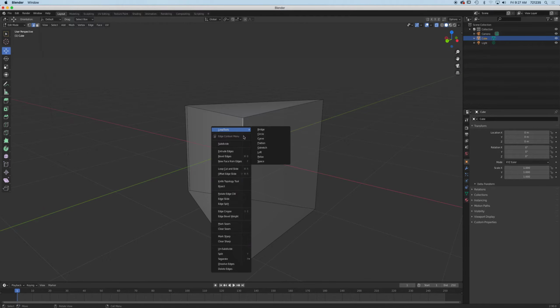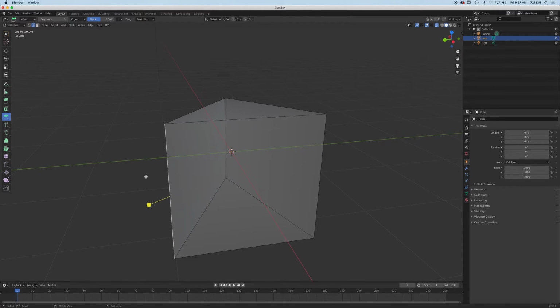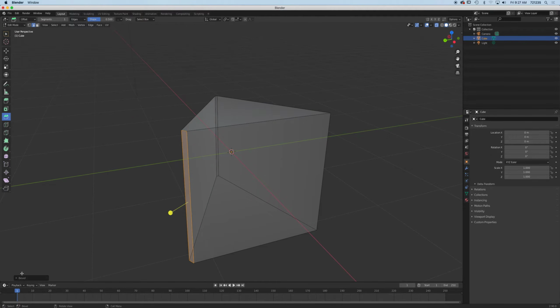I'm going to right click and then bevel, or let's use the bevel tool right here. This one. Okay. While it's active though, that thing will always be on, so I'm going to bevel that real quick. So you see what happened? I just put 2 lines right there, and then you can expand that to multiple segments, but we don't want just one, right? So select that one. Bevel is still active, good. So be careful when you use these tools, they're alive, okay? Until you cancel them by going to the select tool. All right, there you go.